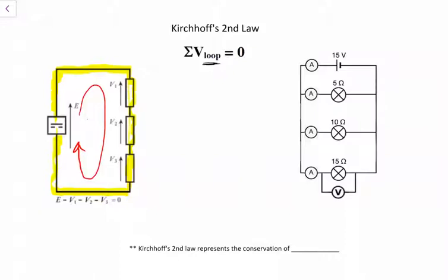I'm going to show you the way that I like to draw the loops, and then you're going to adapt that and use it. So that's one loop. In this series circuit, there's only one loop where the voltage from the battery plus the voltage dissipated in the resistors equal 0. We're not just summing them together. That means that E is positive in this case, and V1, V2, and V3 are negative, which means there are differences between positives and negatives.